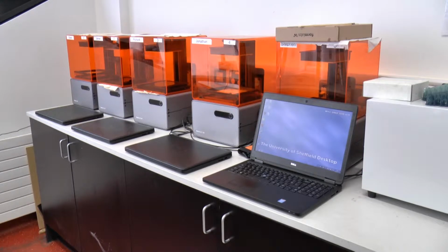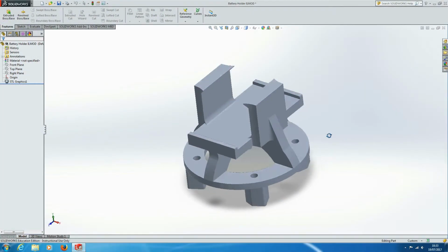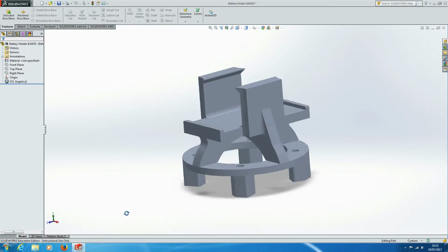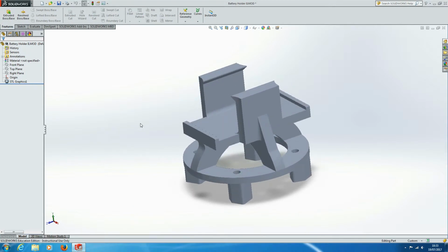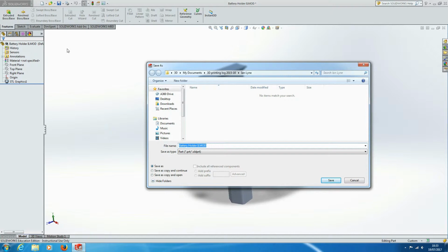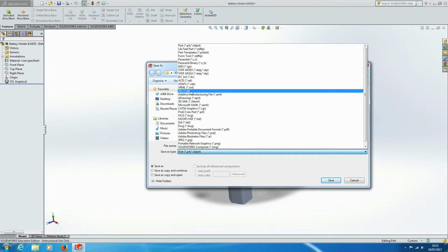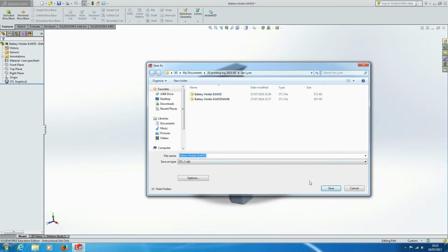You will need to bring your CAD design with you, either on a removable storage device or as an email attachment to yourself. The laptops located nearby the Ultimaker 3D printers can be used to retrieve your file. No matter what CAD package you are using, your design will need to be saved as an STL file. Be aware that there are limits to the type of designs that you can physically print. For example, the total usable size of the building area is only 200 by 200 by 280 mm in size. Anything larger than this cannot be printed.